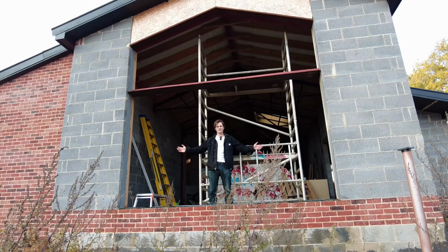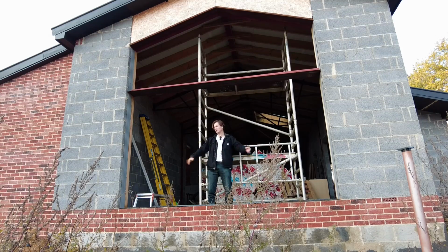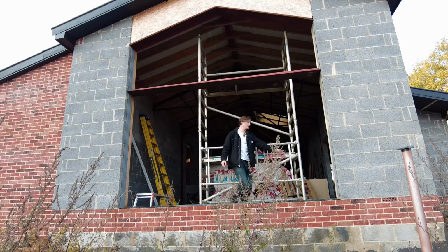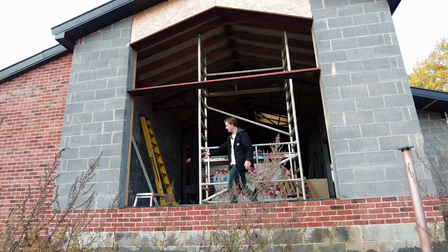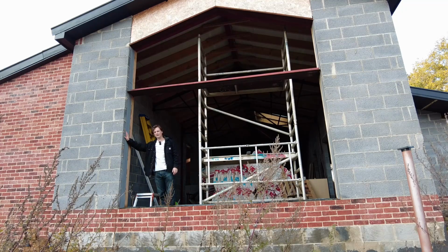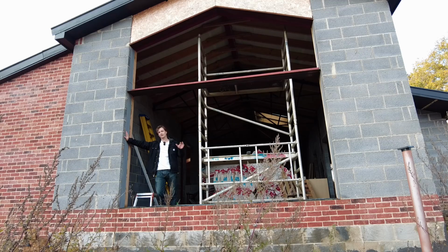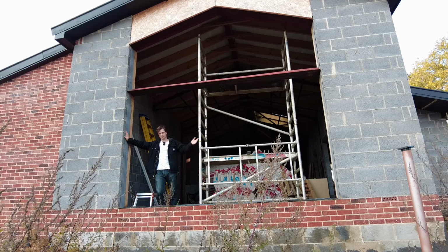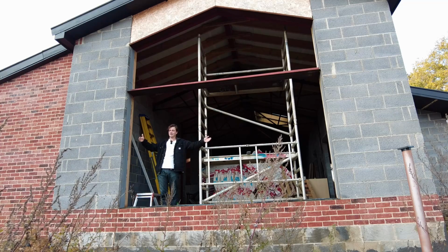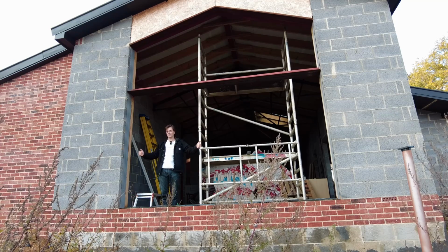So now let's talk about my gable end. These are going to be bifolds, and from here all the way to here is roughly about 3.6 meters. So because that's over 3 meters, I'm going to drop 15mm off of my measurement, smallest measurement between here and here, and then I'll definitely be able to fit them in.